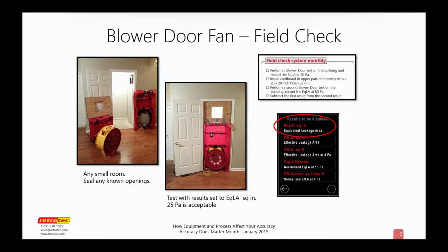Whatever you do, make sure that the room, or the house, is completely enclosed. You want to shut all the outside doors and windows. For those of you who haven't run a blower door before, you want to set it up in the same style that you would if you were running a blower door on a house. Or if you're not running it on the whole house, then you want to set it up in the room, with that room closed off and all the doors closed to the rest of the house.